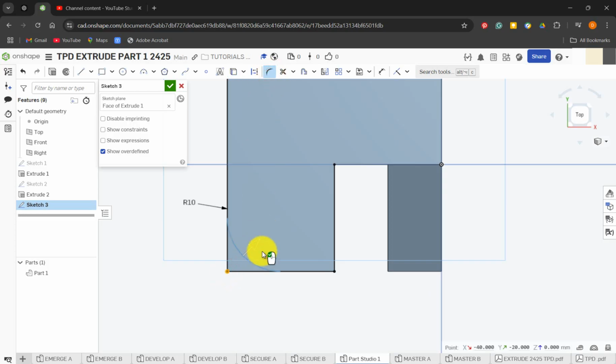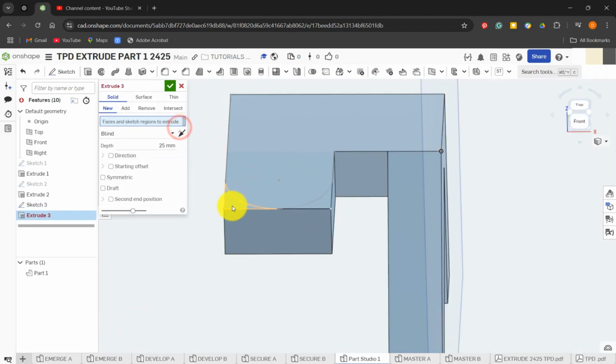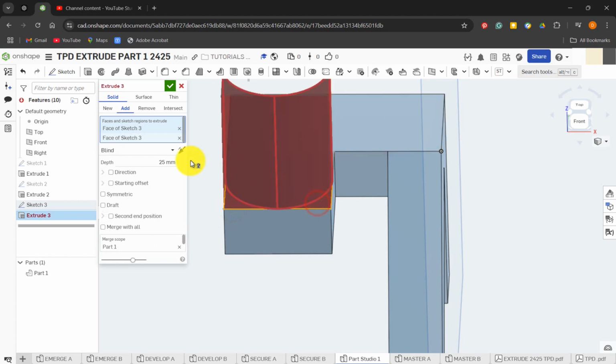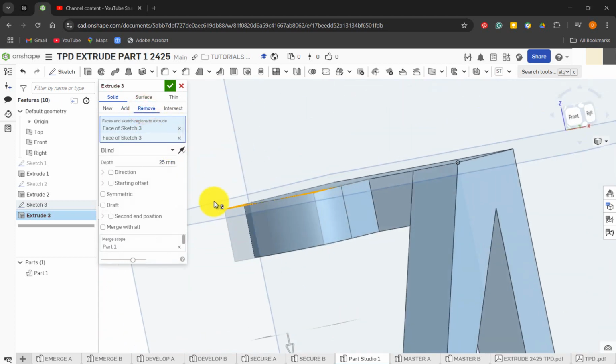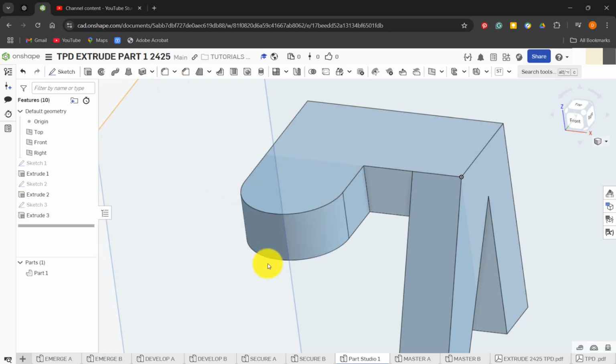So at that point, I've clicked confirm size. I can then go extrude, and we could come in, and we can select that one and that one, and we could go remove, and you could type in -10, so 10mm down, and we could do it that way. That is obviously quite long-winded. Okay, so again, I feel always the easiest option is to click fillet.